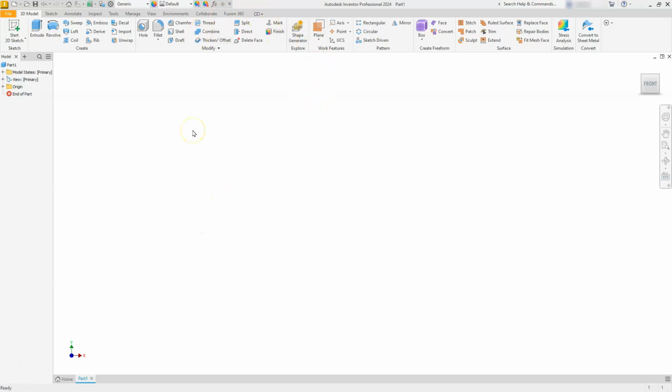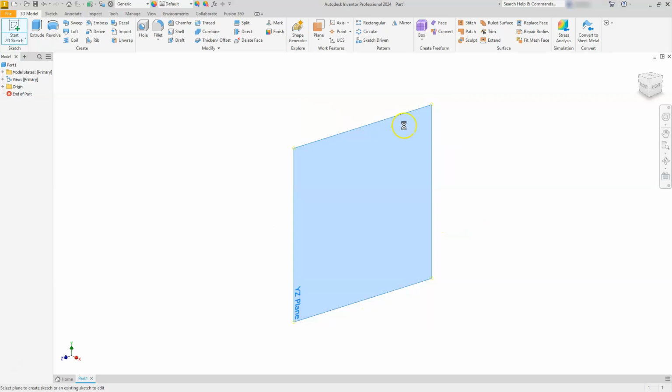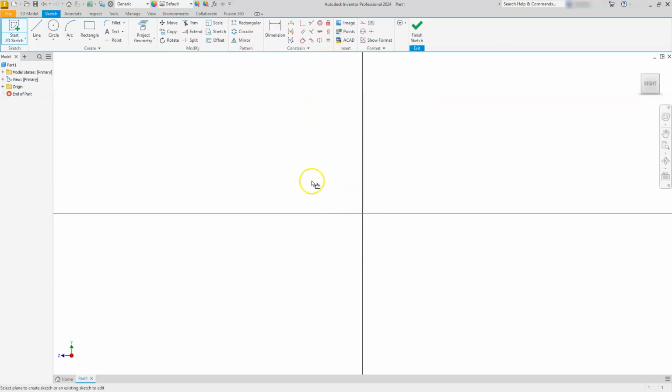Let's go ahead and create a sketch. And I'm just going to start by clicking this button here. And then I'm going to define which plane that I'm going to create this on. And since I'm going to spin it and I want my front view to be facing where I can see all the holes at, I'm going to start it here on the YZ plane. So I'm just going to select on that brown area there. You should see that Inventor should roll around.